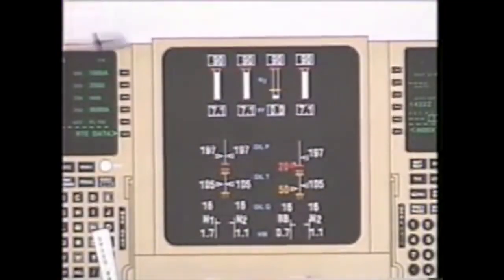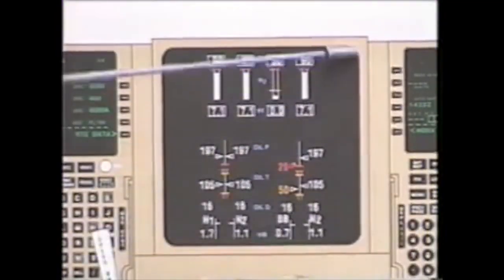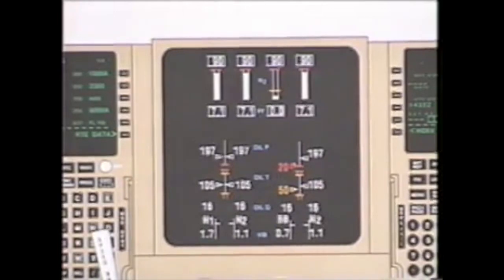Moving down to the secondary or lower ICAS, in this particular picture we have the engine synoptic displayed. You have the ability on the ICAS control panel to bring up any of the synoptics. Engine synoptic here, we have the N2 RPM, we have the fuel flow indication, oil pressure, oil temperature, oil quantity, and the vibration meters. Notice that the oil pressure and oil temperature scales have an amber and red range.